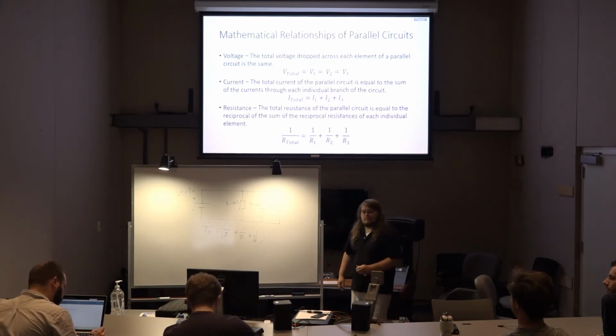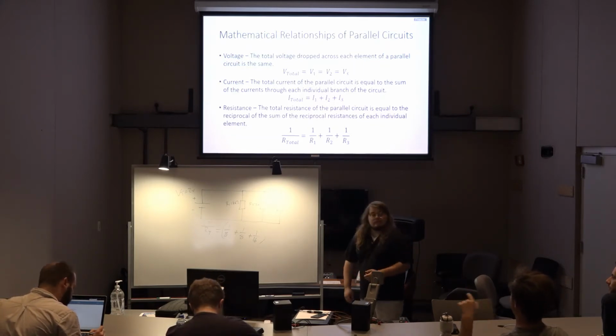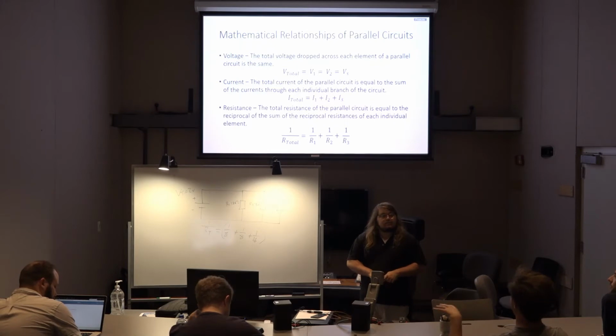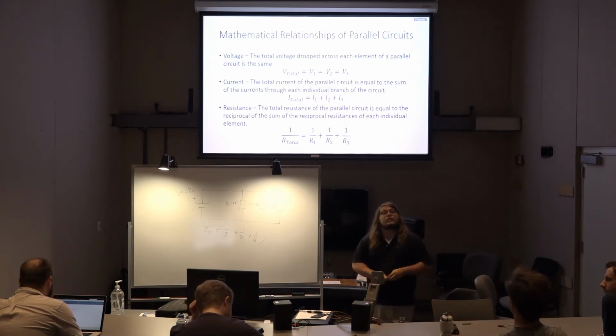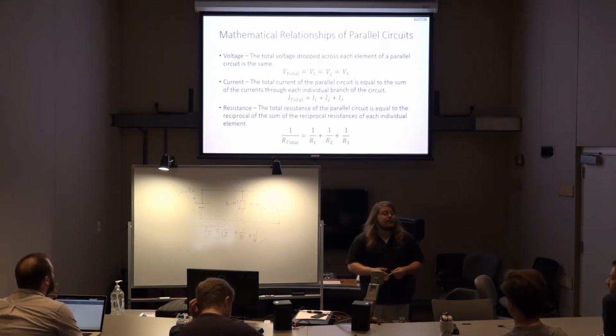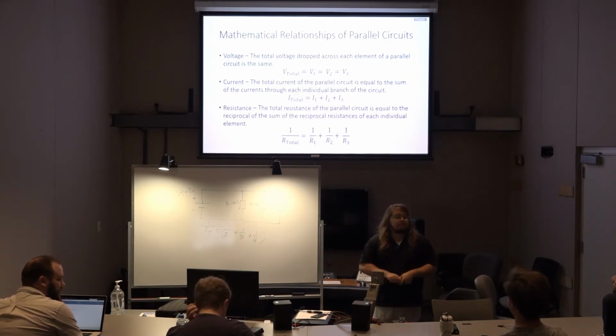This resistance. So if we just add all those numbers together, say we converted them to decimals and added them, that's what 1 over RT is. Correct. So if you want to find RT, you take one divided by that number? Correct.